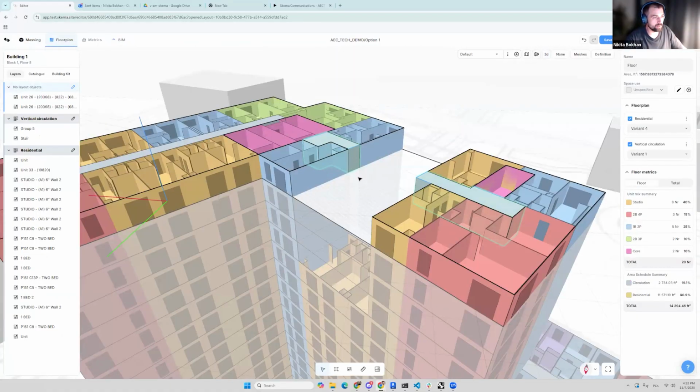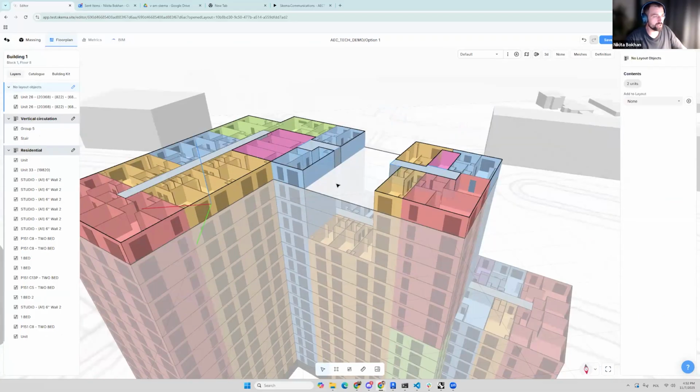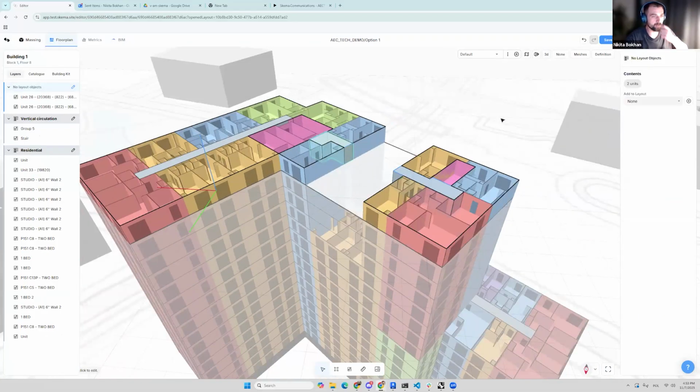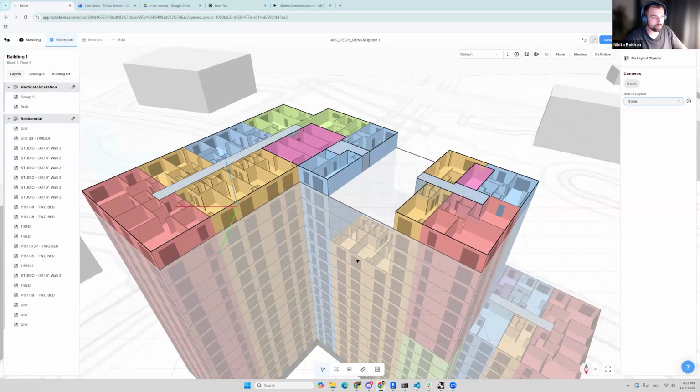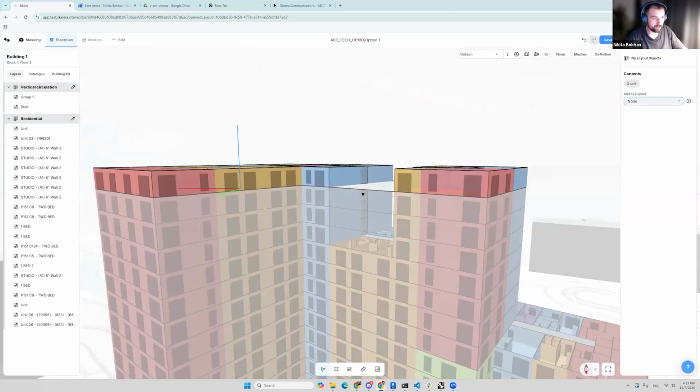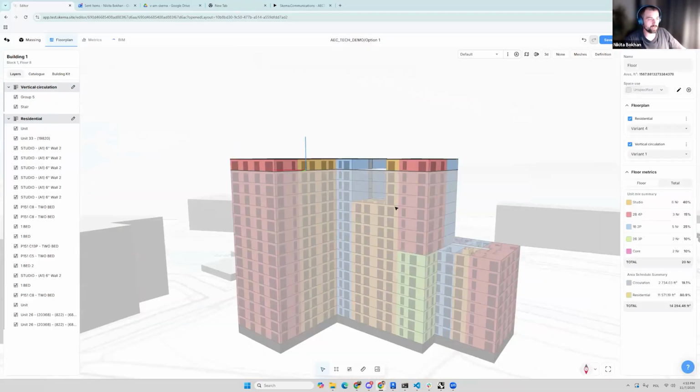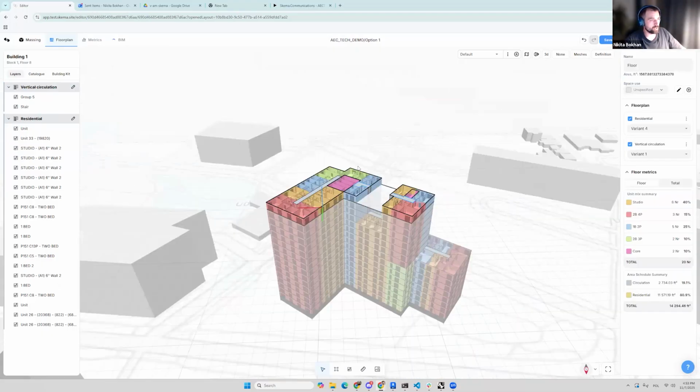This is kind of the latest feature. The object that I edited here was created only on this specific floor, meaning that I need to move it to my residential floor layout, and now it appears on all the variants. So let's consider it as logical groups of the floor plan layouts and their attachment to the particular floors. Let's save it.